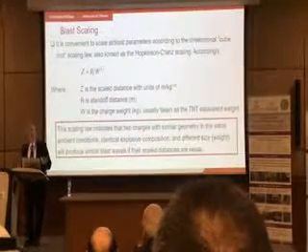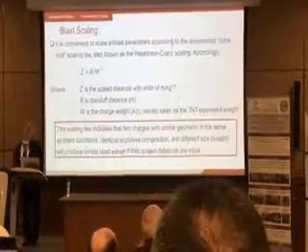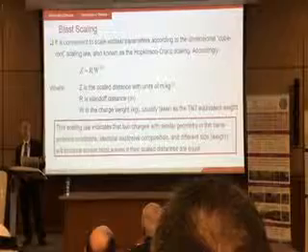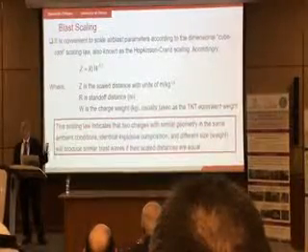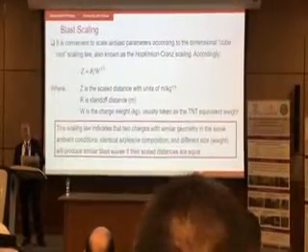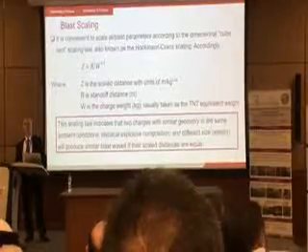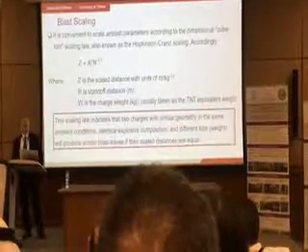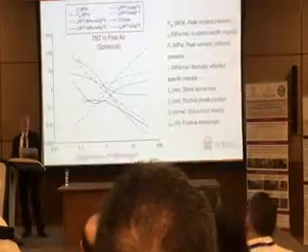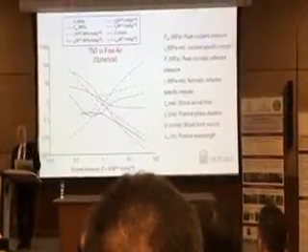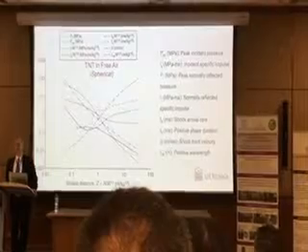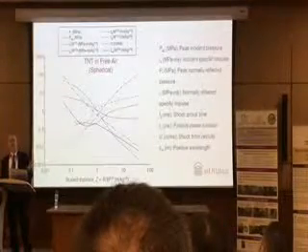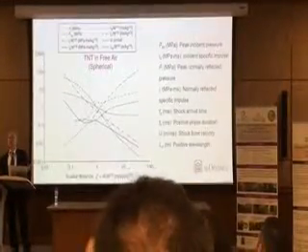That non-dimensionalizes things. So I don't need to come up with design charts for 100 kilogram TNT, 500 kilogram TNT. I can come up with non-dimensionalized term, which is referred to as scale distance Z. Now, if you know Z, then U.S. Army, it was a classified information, but they released it.